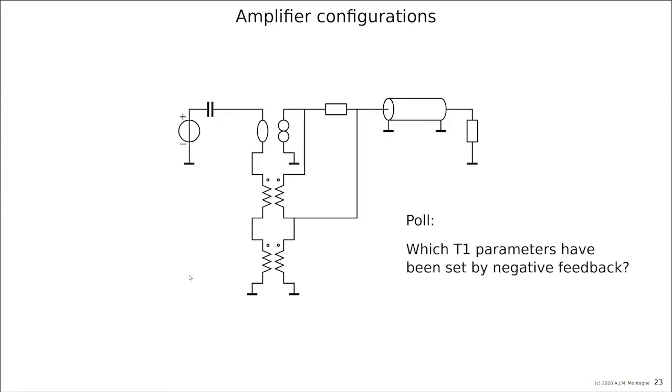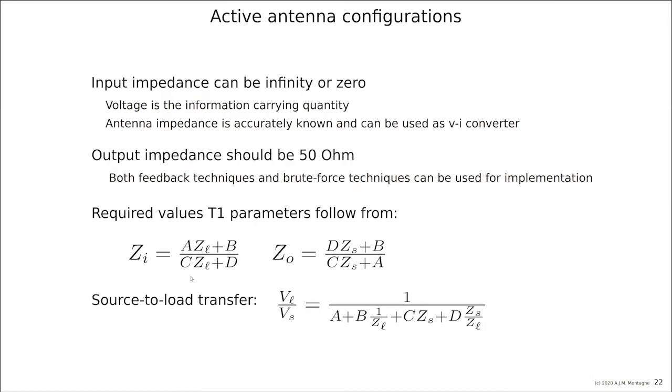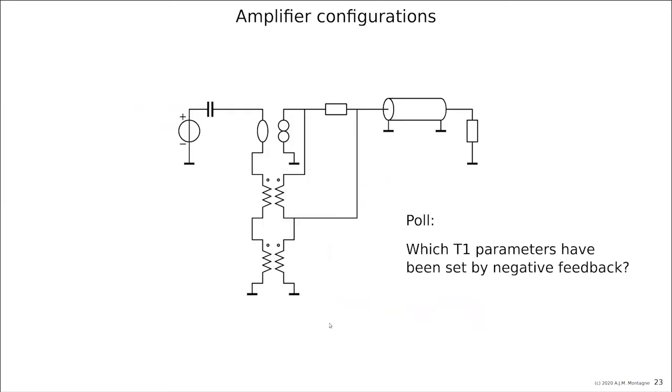And if we now go back to our expression, then you see that A and B are set by feedback, C and D are 0. So the output impedance is B over A. And by knowing A and B, and since ZL is the output impedance, we also know the voltage transfer and can calculate from that A. And then we know B. That's the sequence of designing it.